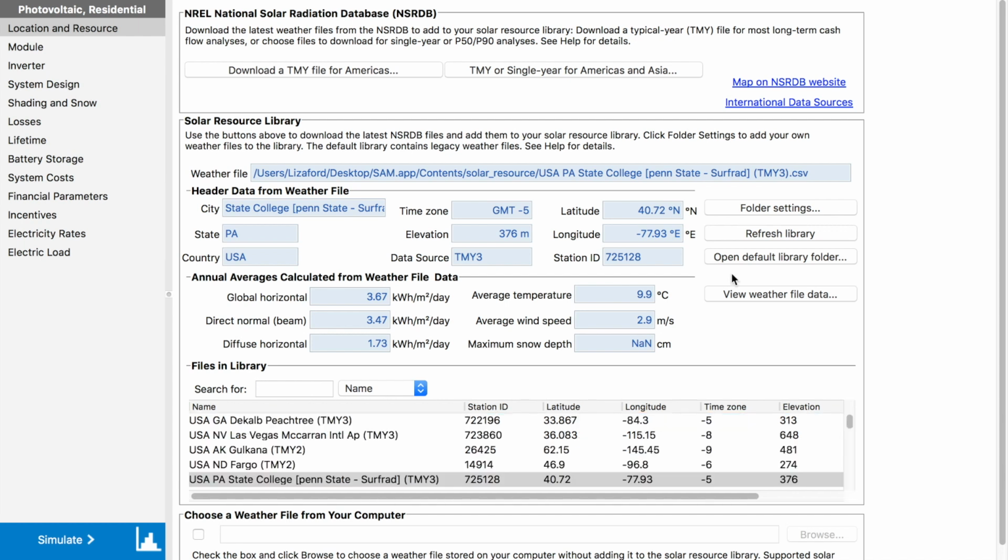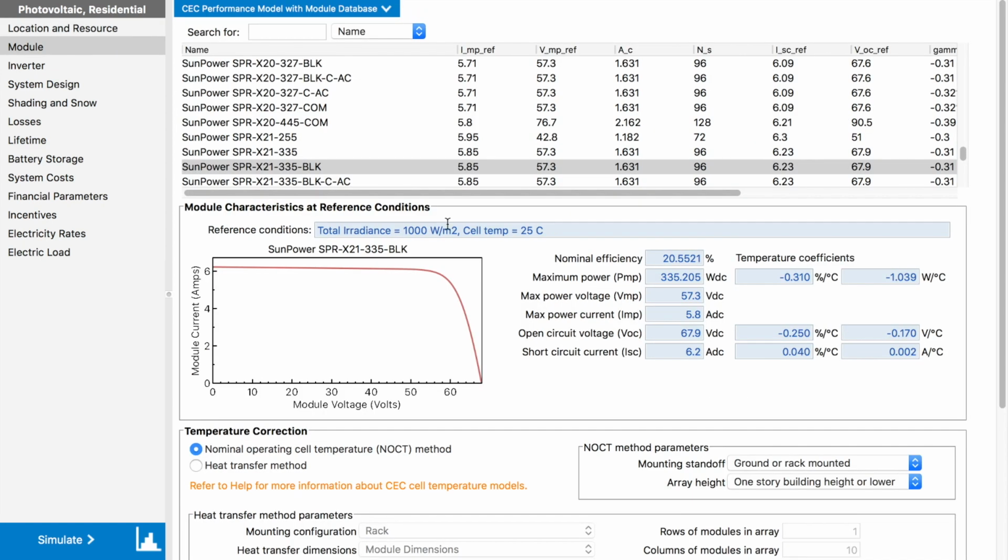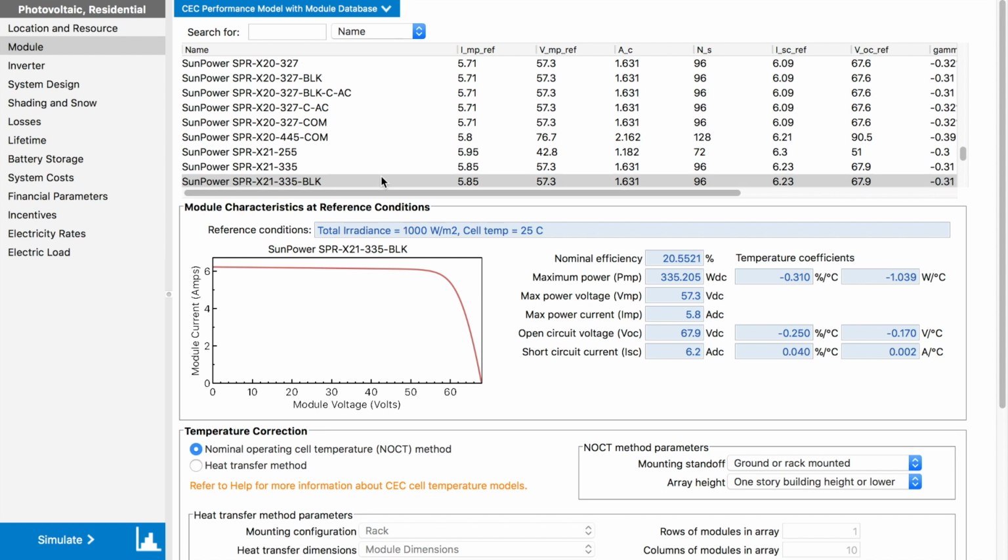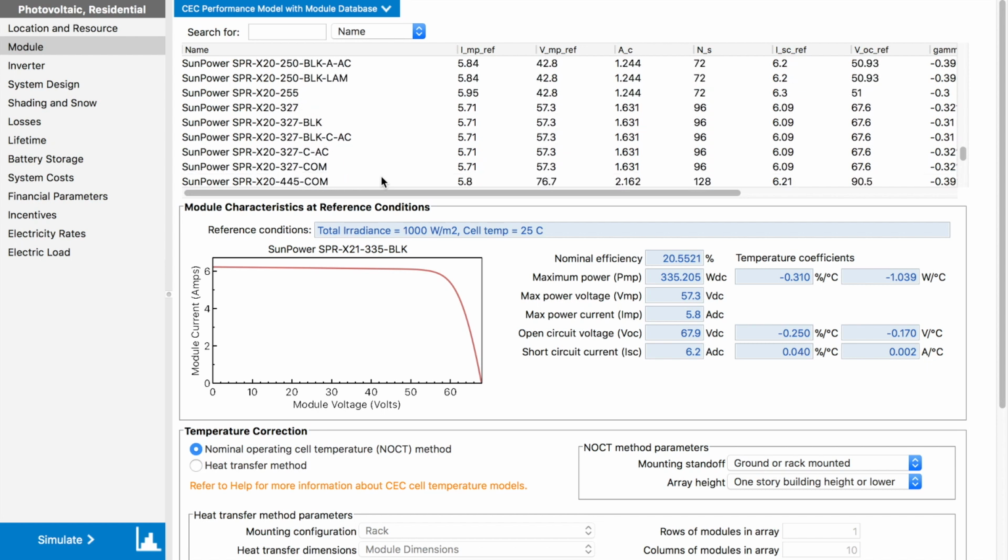The next step is selecting a module that has to do with the specific price point of the client and how much they value price over efficiency and aesthetics. Usually you present the client with two different options: one panel with less power that costs less overall, and another module option with more power that is more expensive, and allows them to choose whether they want to lower the cost or maximize the power. The manufacturers typically produce two different levels of the same module design in order to give consumers a higher and lower end purchasing option. This is the same as buying a more expensive washer and dryer that will wash and dry your clothes much faster than the lower end, cheaper model. But some consumers will still choose the lower end model just due to the price point.